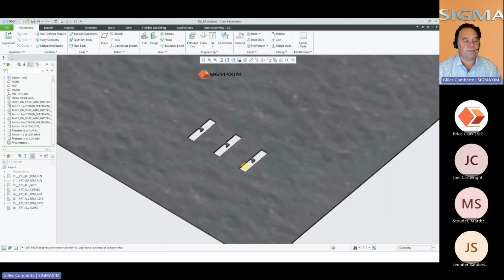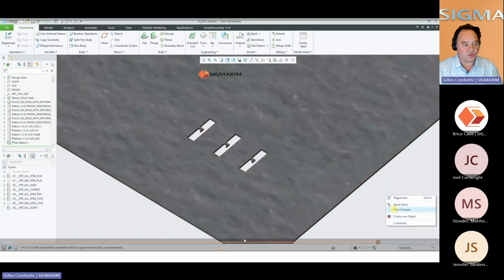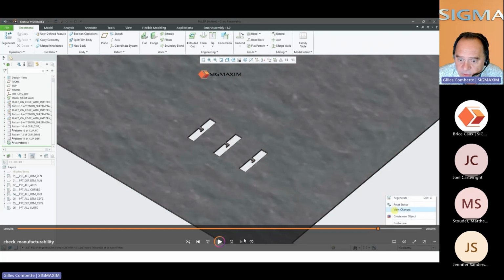But in reality, the other solution that receives the DXF file, you may help it by sending it symbolic representations, symbolic shapes. For example, here, the form was not able to travel through the DXF, but this symbolic shape is just a regular 2D contour that will be able to travel through the DXF.